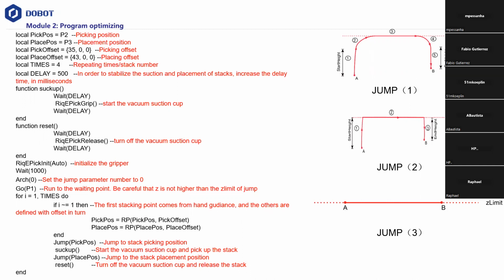You want to make a turn so it won't stop, right? You don't want to stop every time you change your direction. You have to either add the command CP to make it go around, or you can use this function here. You can see it here when you go to jump. One of the dimensions is how rounded you want the corner turn to be.